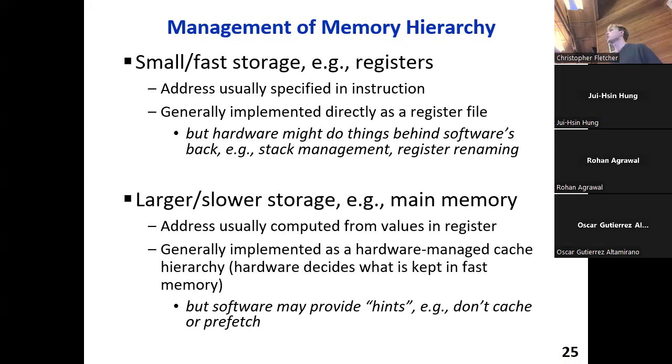In other words, these memories are content addressable, and hardware manages when to fill and spill and evict lines from these lower memories so that you, the programmer, don't have to think about it. And it does that potentially behind your back, because speed is less of a premium for these larger memories. So it's a trade-off in access latency and programmer complexity.